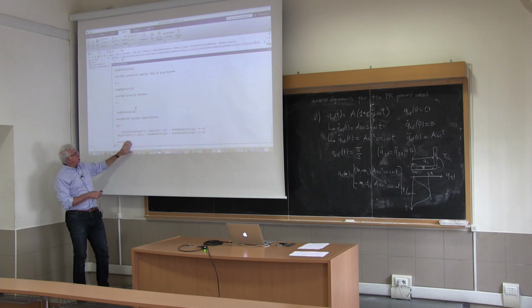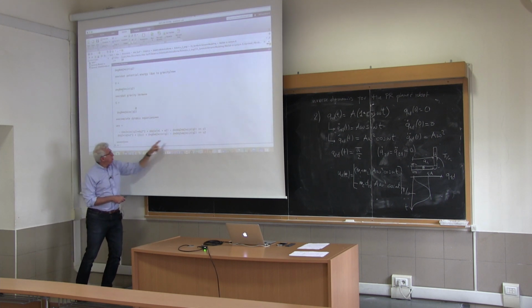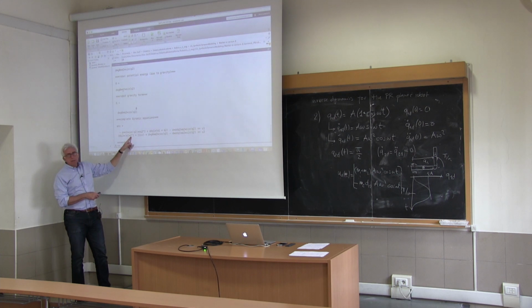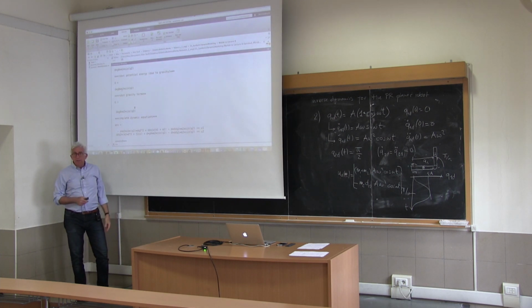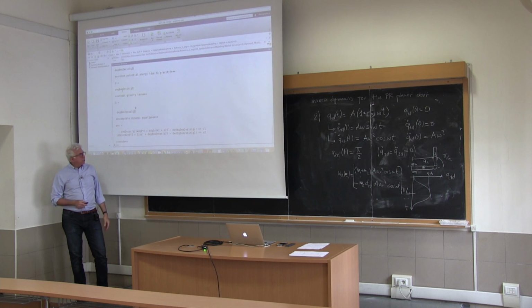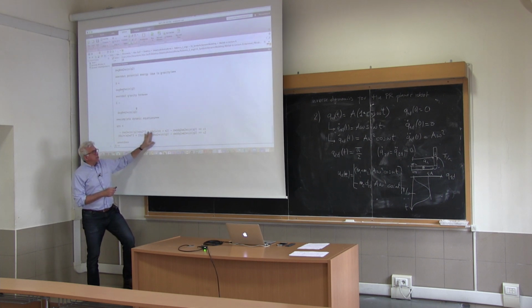In the second equation, you have an extra contribution due to gravity, while the other two terms are weighting the first and second acceleration. There are no terms in the quadratic velocity because we have seen that there are no centrifugal nor Coriolis terms in the second equation. And this is exactly the same result that we had. The additional term because of gravity is only this.